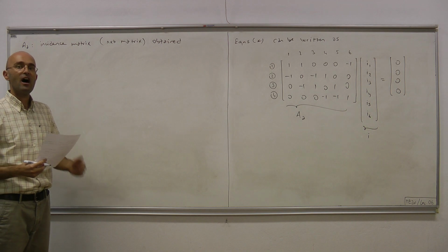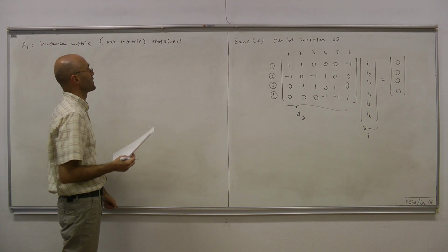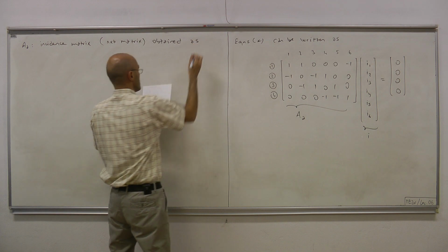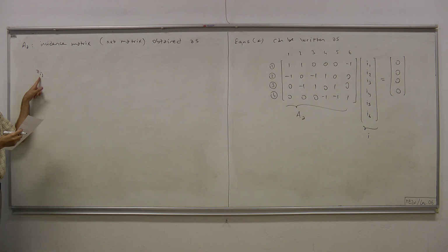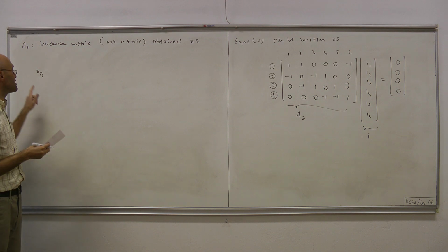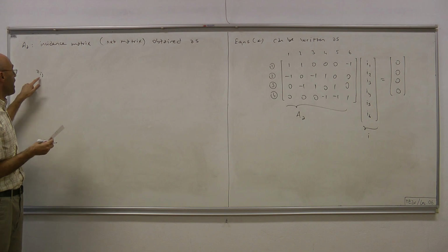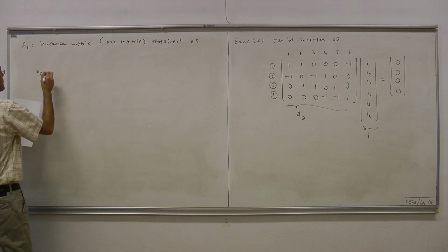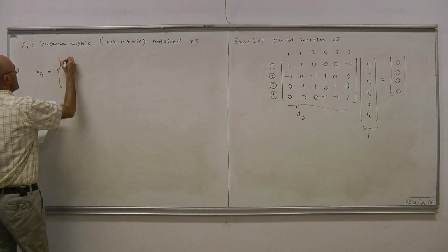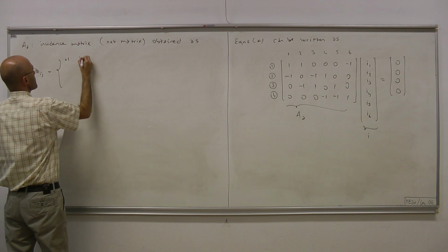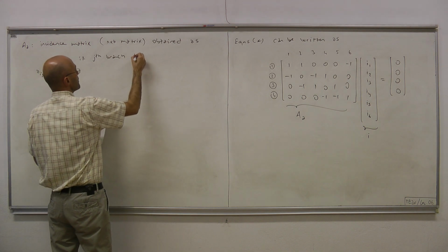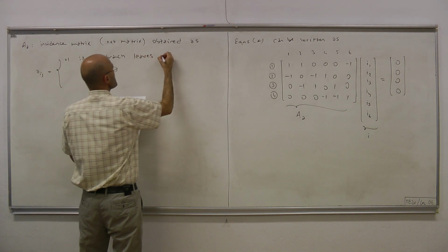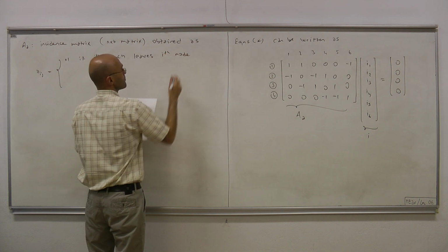It's more or less clear how it's obtained by looking at this simple example. It's obtained as follows: Aij, this is the ijth entry of our incidence matrix. Ijth entry means the entry corresponding to ith row and jth column. The entry is +1 if the jth branch leaves ith node.